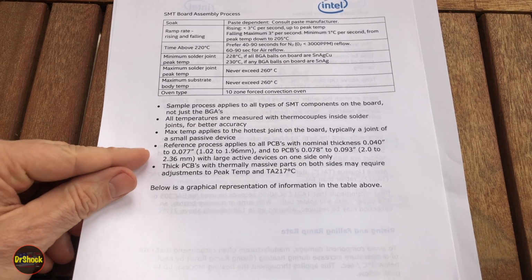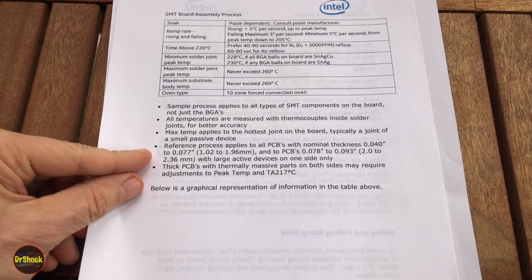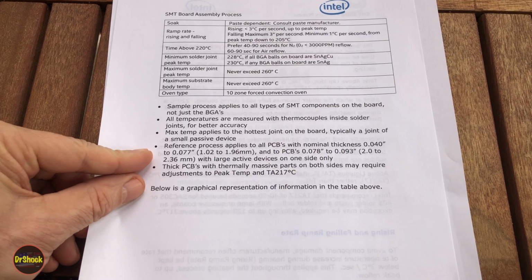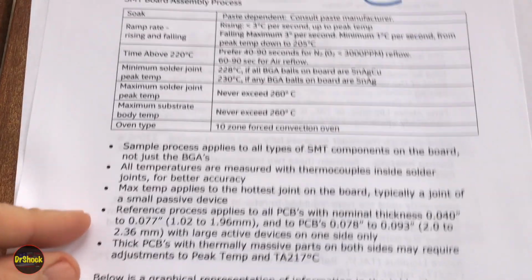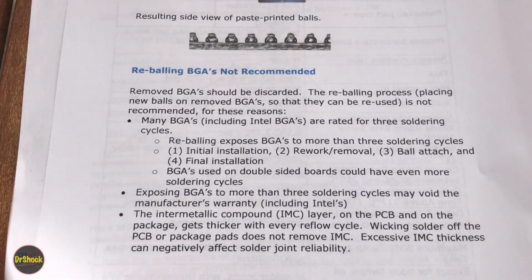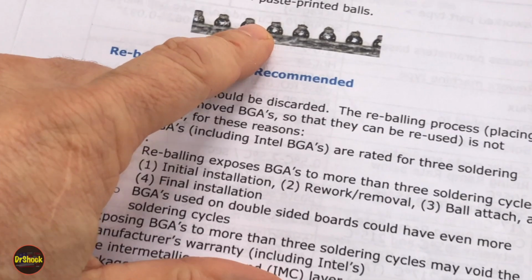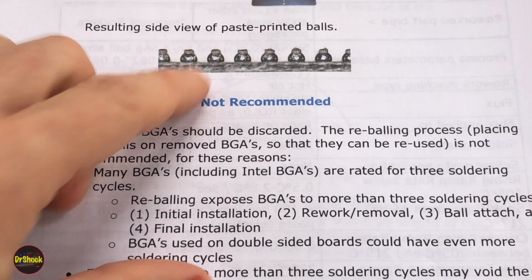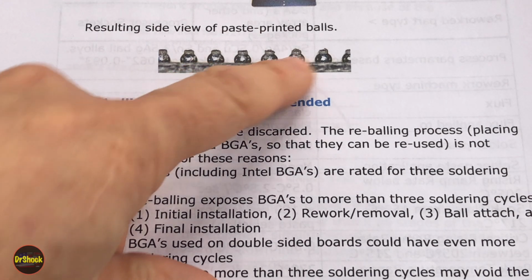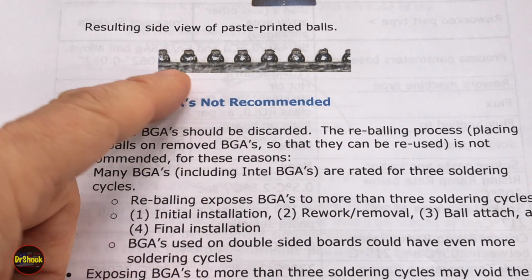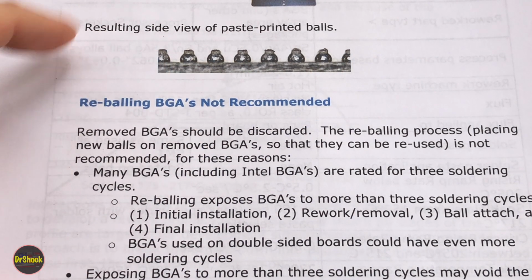There's also some information here just on some various specifications about the device. I zoom in here, but the main thing we're after is when you look at these balls that are underneath, one of the things that we're trying to do is reliquefy these so that any cracks or damage on them can be rehealed. And you can do this a couple of times. It's called a secondary reflow.